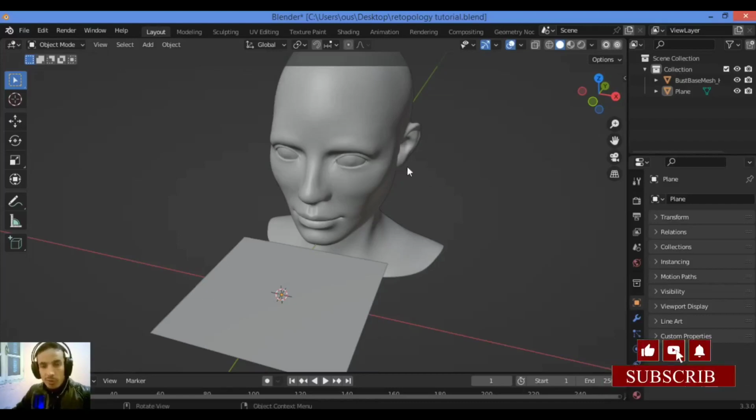You should also consider, when doing retopology, deformation topology rules: the edges of our grid need to be parallel to the axis of deformation. The axis of twisting should be aligned with the edge flow. You should always put at least one row of faces between a pole and the specific areas of deformation. You can watch my previous videos in order to understand all these rules before starting